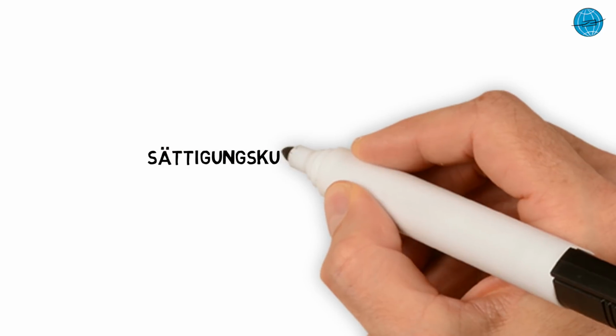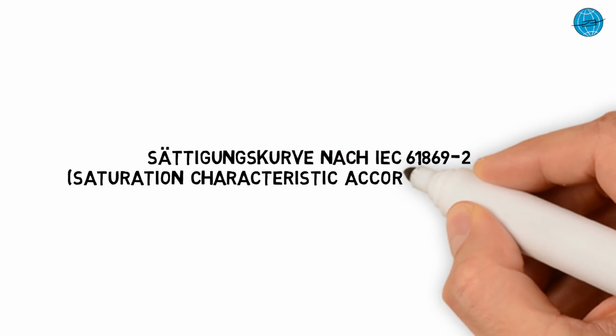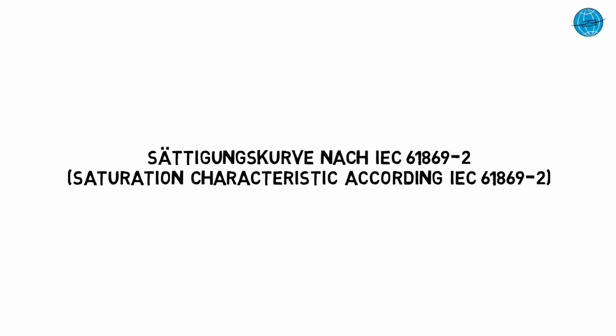We now want to record the saturation curve according to IEC 61869-2, both with the MVCT and with the CTA, and use the following two transformers for this purpose.